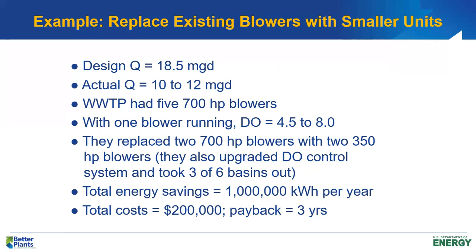Their energy cost savings was $67,000 per year. The total cost of putting in these two 350 horsepower blowers was $200,000. So the payback was about 3 years, and this turned out to be quite effective and made the aeration system much more efficient.